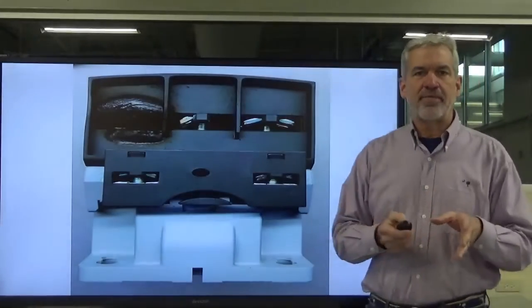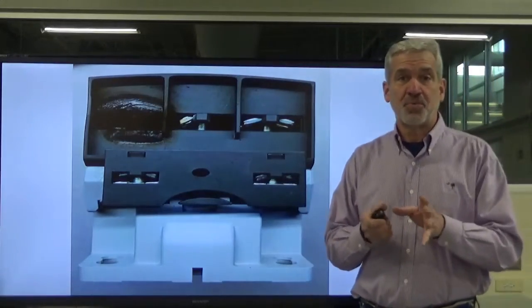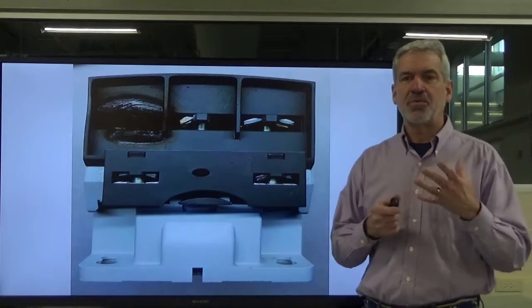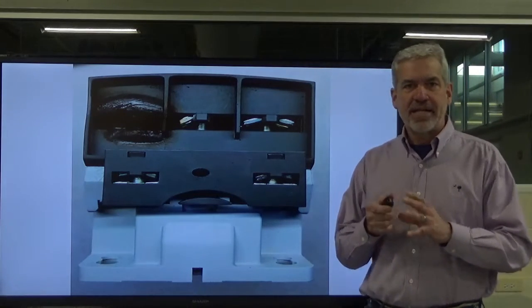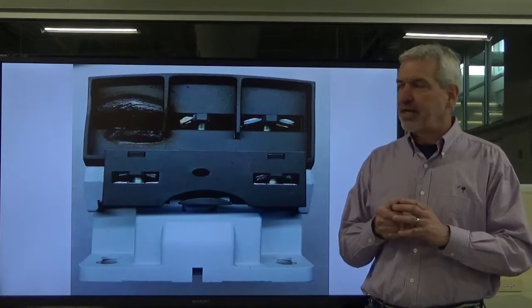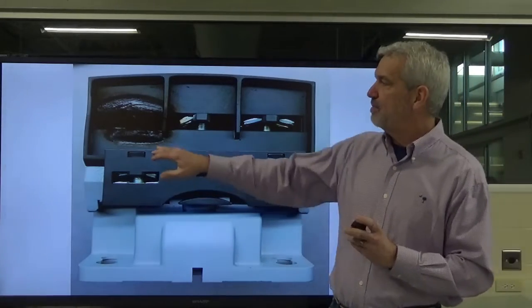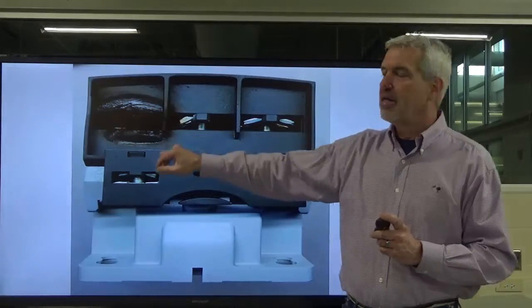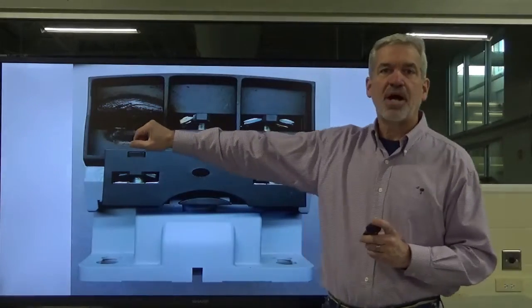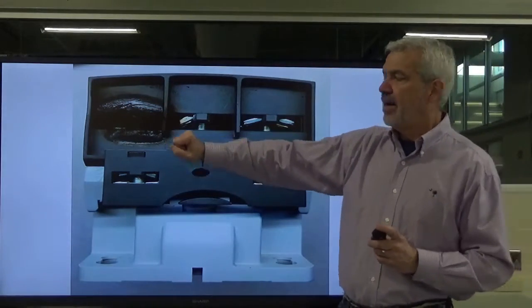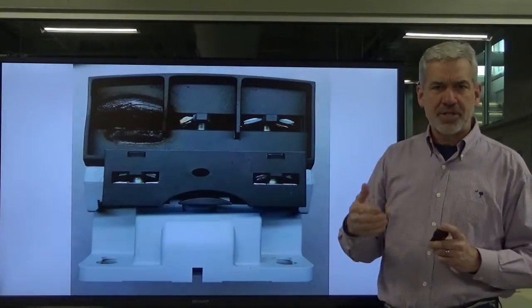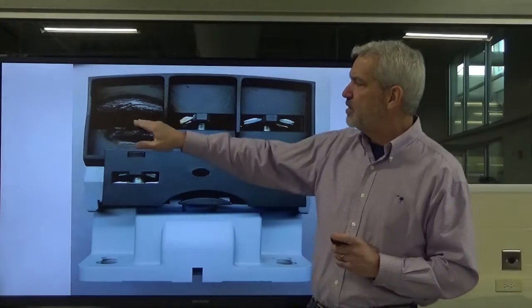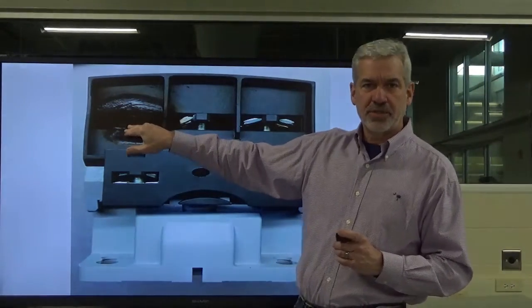And what they wound up finding themselves was really good. They were not going to wait on me. I couldn't get down there that day. So they did a little looking and a little checking around, and sure enough, this is the actual picture of the contactor. And you had a burnt lug right here. You had a very loose connection right here that got real hot, okay? So, and they had lost another one of these prior to this too. So this joint right here got loose.